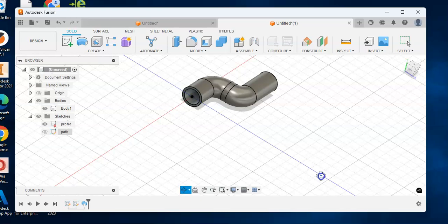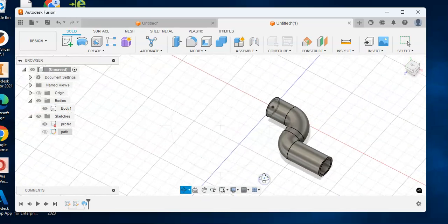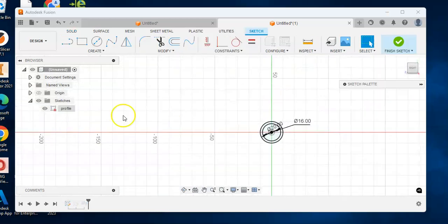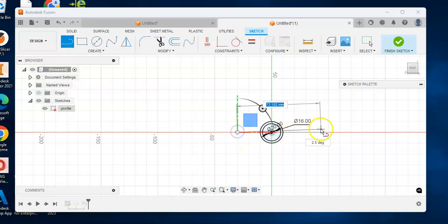It's a zigzag pipe. Now, if you were to actually print this object on a 3D printer, what you would find is that the support material, which goes inside and keeps the filament from collapsing, would be very difficult to get out of the middle of the object, especially if this center part of the profile was longer. So that leads us to say that maybe what our profile really wants to be, instead of a pipe, maybe we'd like to have a trough.